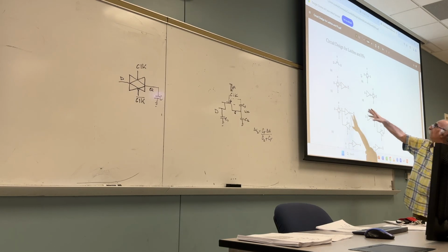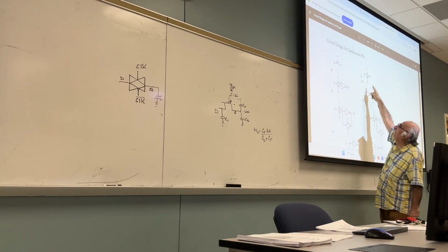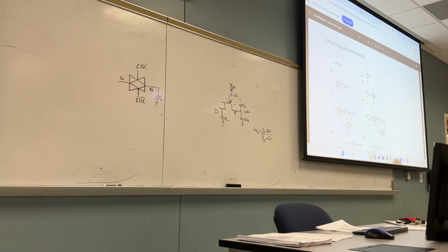So what did I do here? I want you to tell me what difference between this one and the above one. What is the difference? One added an inverter at the output, and the other one added the inverter at the input. Yes? To buffer against noise. Did you get it or not? But in doing so, the latch became an inverted latch.